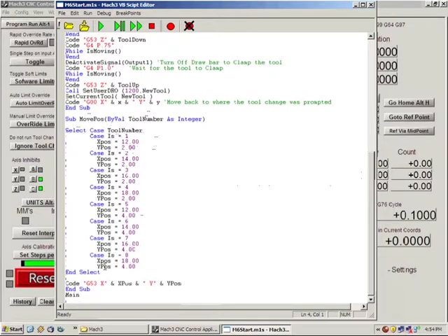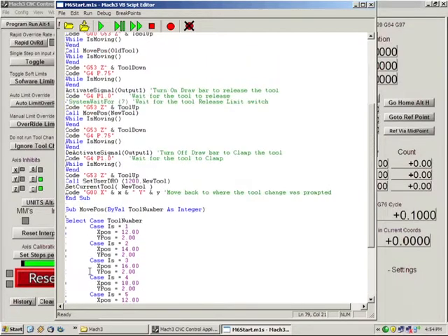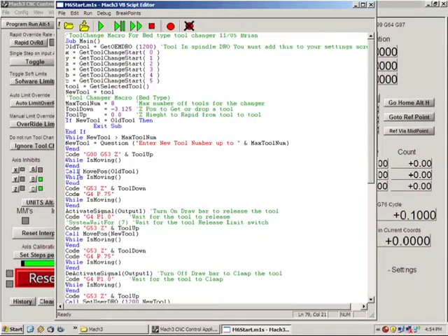At the end of this code, you'll see G53 X position Y position. So this will move us to these positions, and then it exits and it goes right back up to where it started. So that break there basically just moves us into whatever tool position we ask for. It makes the code a little bit easier to run, but it's very important that you understand what it's doing, because that's where you edit your tool change positions. So it waits, it moves the tool down, and then this G4P.75, we're pausing and waiting for it to be into place, and just waiting for 3/4 of a second.